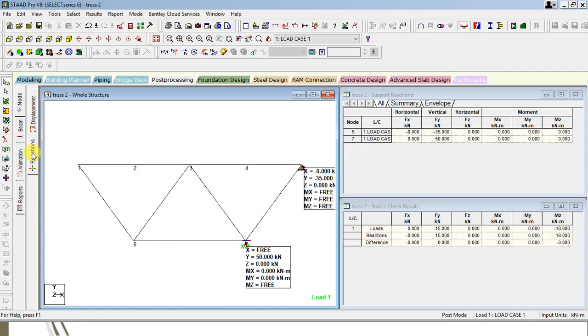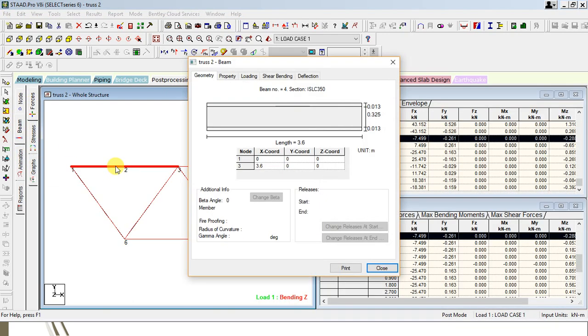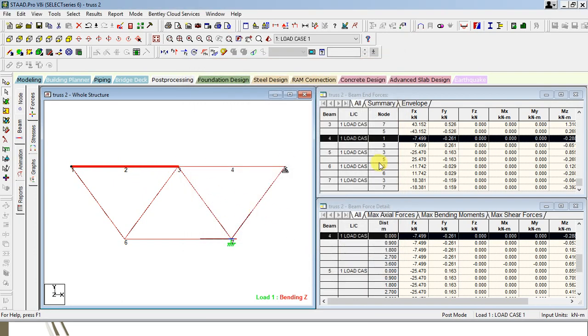Okay, now here also in reactions, in forces you will get this. When you are selecting this beam, here that row will get highlighted. So in this you will get these reactions in x direction and y direction. So therefore total reaction you can calculate as the under root of summation of fx square plus summation of fy square, that you will get the force in that particular member.